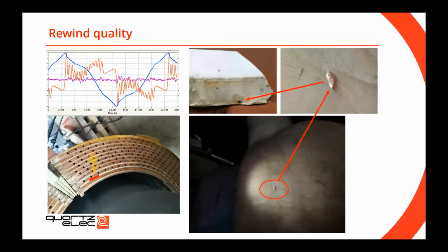They brought it back to the factory, took the retaining rings off, and they realized, indeed, there is a fault, so they found it. This is the palm of a hand, and you can see that tiny little debris. We knew afterwards, when we analyzed what that debris is, that this is an alloy that we use to braze two copper joints together.